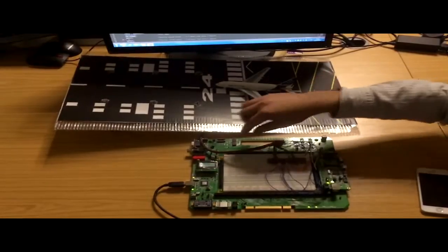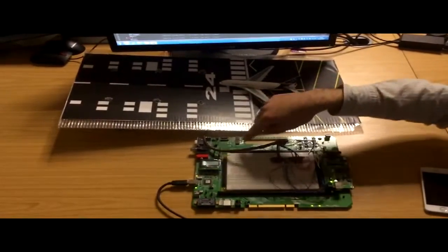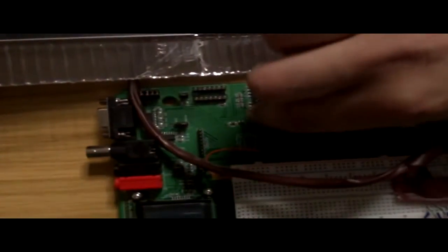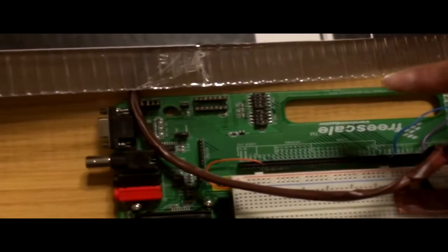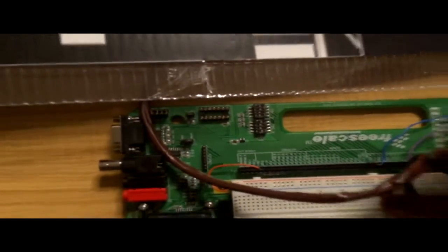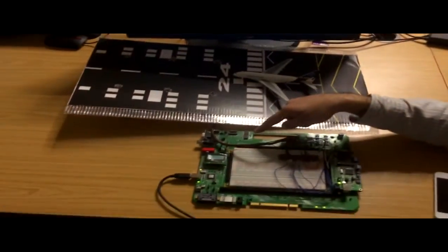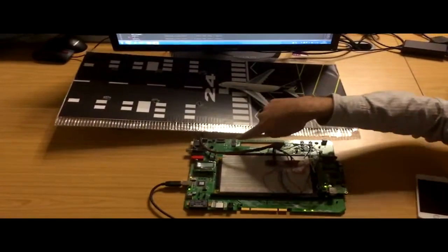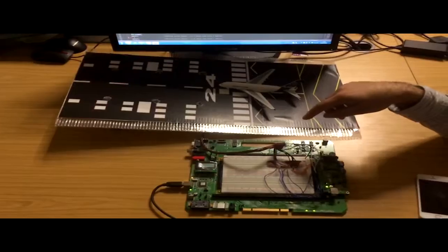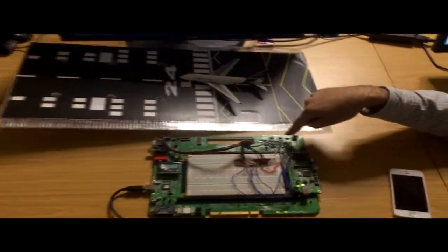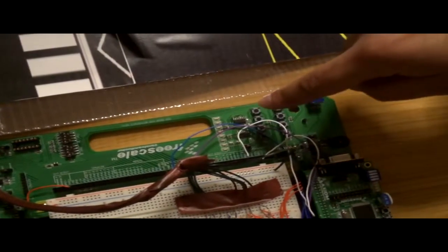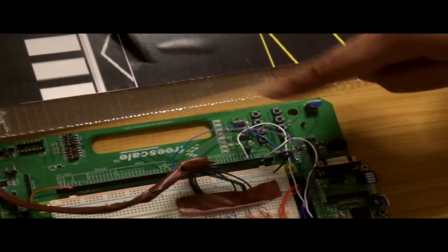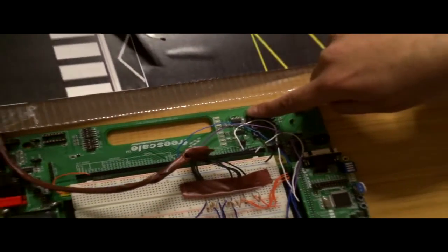So now I turn the switch on to make the whole system on, and the other switch is obviously for the manual and automatic mode, which we will go through later. So now the system is on and in the manual mode. That means that by manually pressing these 2 buttons, which increment the LEDs on and off, I can switch them on and off based on the light level.